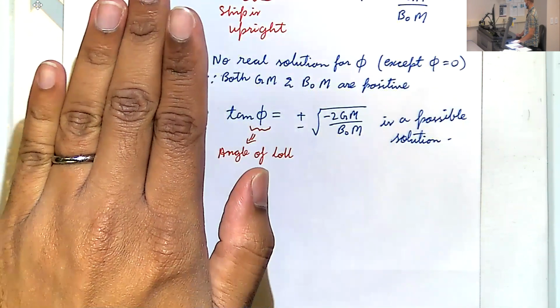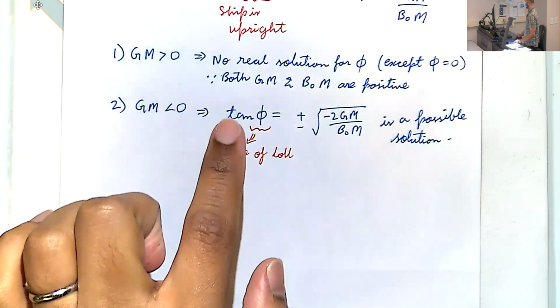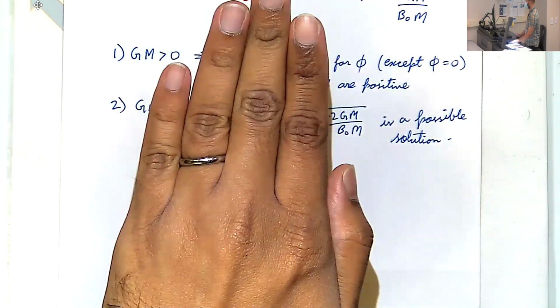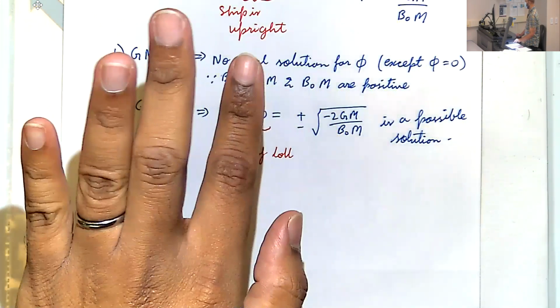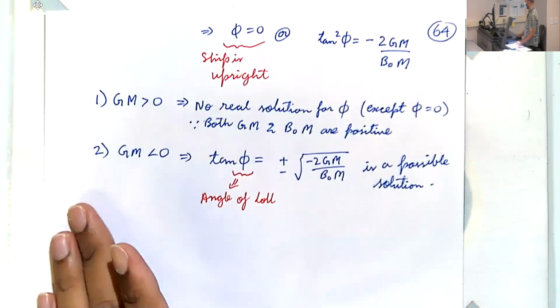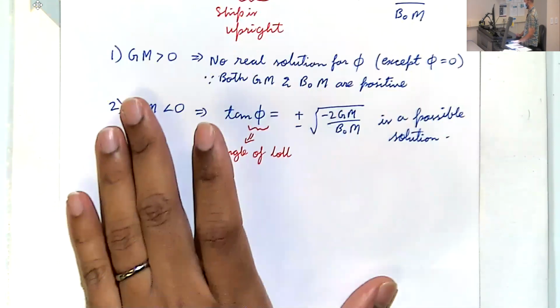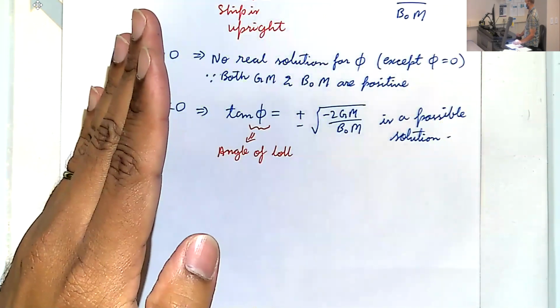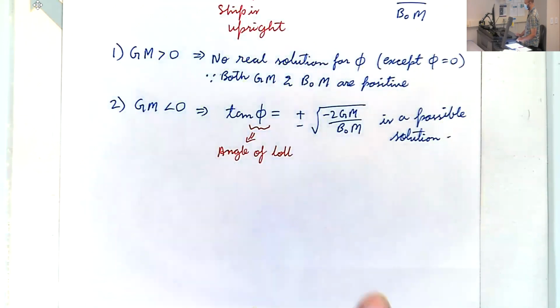When it started taking on water, its stability decreased to below 0. So it started capsizing. But because we're working with large angle changes, it won't capsize all the way. It'll heel up to a certain point, and then stay there. That's called this angle of loll.